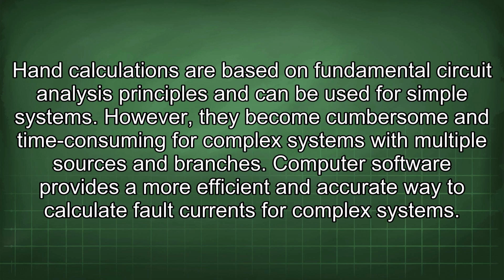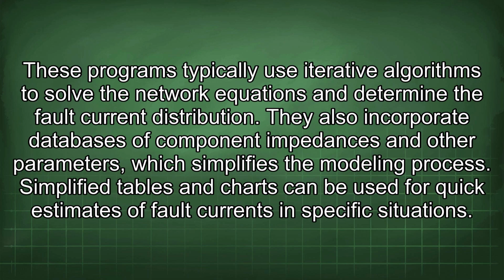Computer software provides a more efficient and accurate way to calculate fault currents for complex systems. These programs typically use iterative algorithms to solve the network equations and determine the fault current distribution. They also incorporate databases of component impedances and other parameters, which simplifies the modeling process.